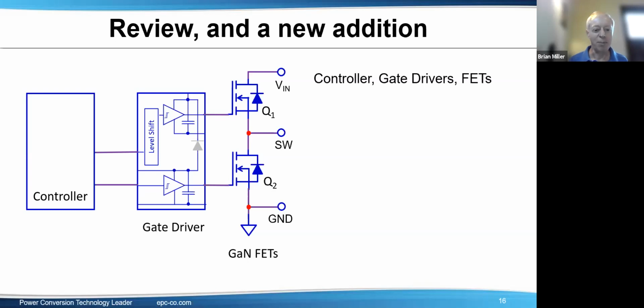Another reason is if you put an external parallel diode, a Schottky diode, around this, you can say, okay, that's good. There's no reverse recovery in that diode, but there is capacitance. And the capacitance of any kind of power Schottky is something else that just adds output capacitance to the GaN FET. So with low frequency, it might be okay, but that's something that would take a good analysis.